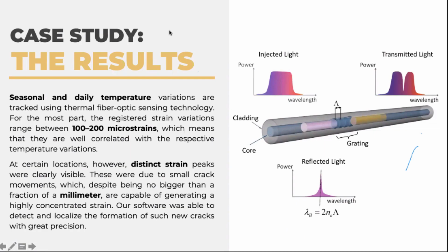So mainly we are measuring the strain, right? So then, based on this data, we can predict if there is anything happening at any point. And because it's distributed sensing, across the whole fiber we can have a lot of monitoring points, which makes it very unique and very easy to install at any type of infrastructure. And we can pretty much cover the entire infrastructure and the critical points of it with just a single line of the cable.